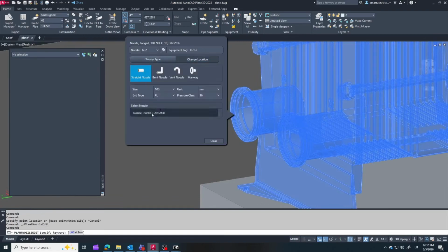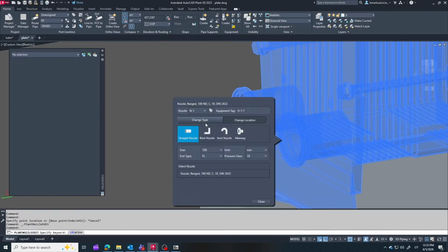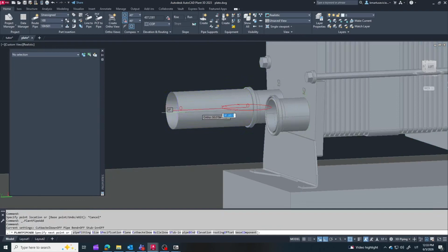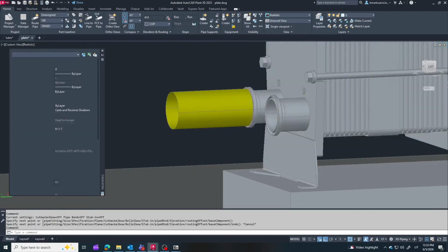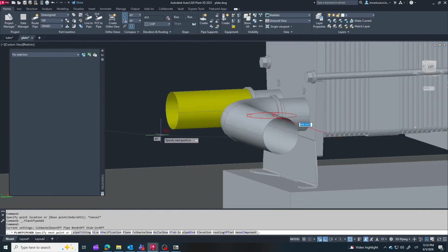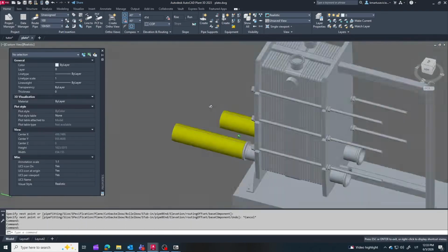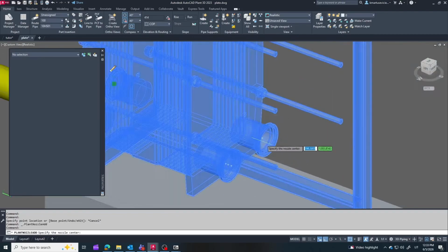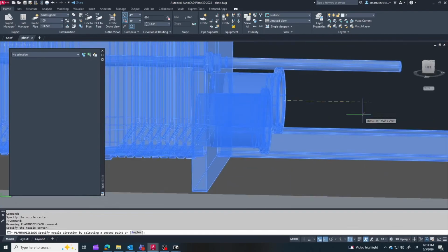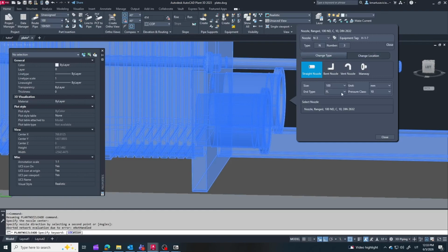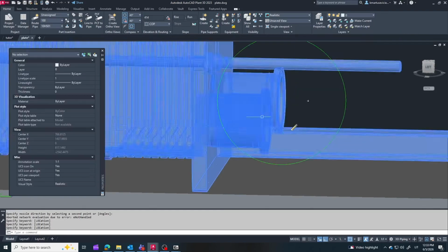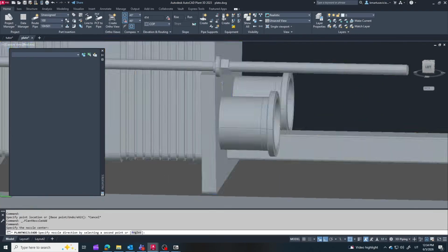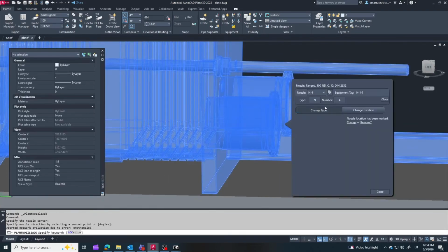I'm setting the nozzle connections to plain here because in real-world industrial setups, these plate heat exchangers are very often connected using special clamps or quick connect couplings rather than standard flanges. While I'm adding these next two nozzles, take a look at how long these tie rods are. This back plate area must be kept completely clear. Periodically, the maintenance crew will need to unscrew these long bolts and slide the plate back to clean or replace the internal plates. If you route piping directly behind it, they won't have the physical room to service the unit.